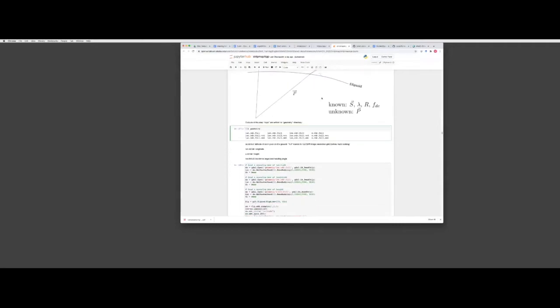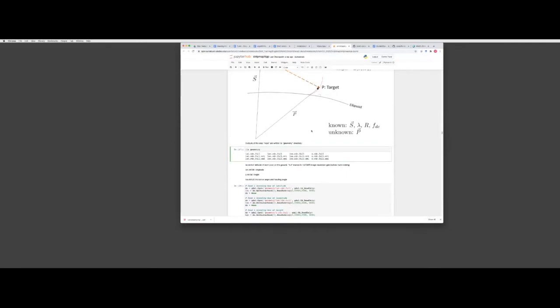So after running this step, another directory is created called geometry. And inside geometry, you will see that you have lat.rdr.full, lon, and Z. Lat stands for latitude, and Z stands for height. So the primary output of this computation is basically lat, long, height of each pixel of our SAR image. And those computations are done for the reference, based on the metadata of the reference image.